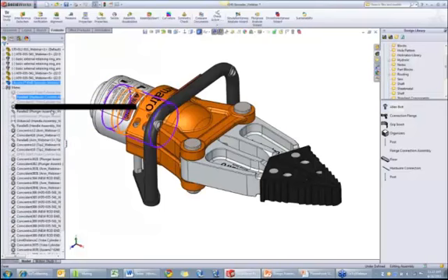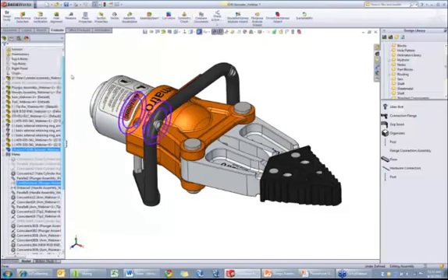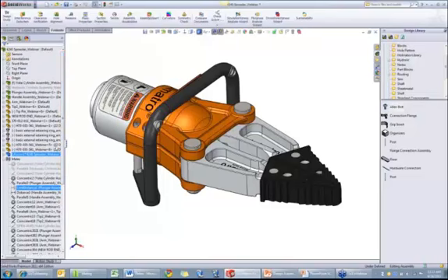Whether the parts are in a subassembly or not makes a difference to the explode view. Now, if you want to move these components around, you can move them anywhere you want because the software rebuilds or resolves the locations of these components simultaneously. So if I move this, I can move the subassembly up here to where the other subs are, but I don't want to place that part into this subassembly. So I'm going to hold down my Alt key on my keyboard so that it just reorders it. It doesn't put it inside that one.